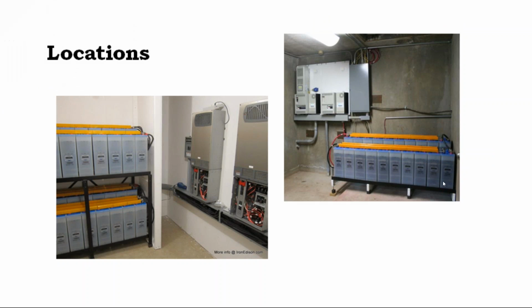For that matter, they've made this little terminal not particularly accessible. Now, whether an inspector would disqualify you or not, I don't know, but the point is you can't just shove the batteries up against a wall. A better layout for this battery bank would be to rotate it 90 degrees and have that part of the battery against the wall and then have the battery rack come out from the wall so that you could actually go and service each terminal of the battery.